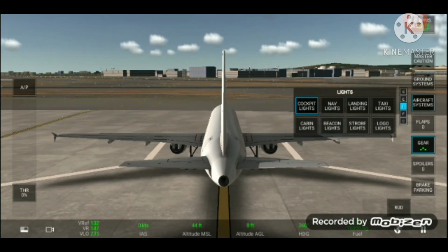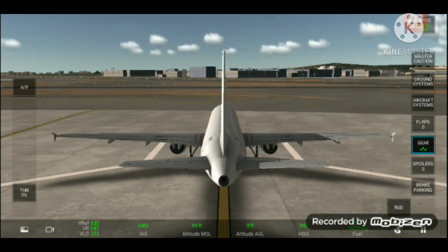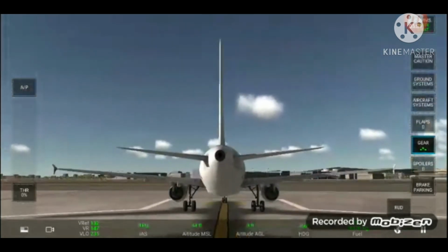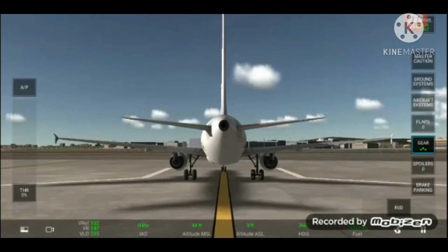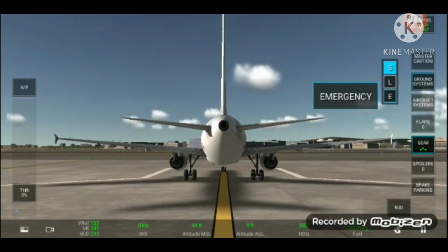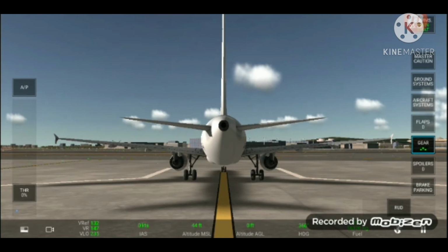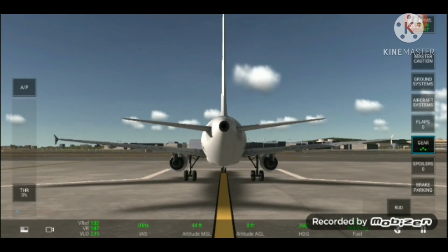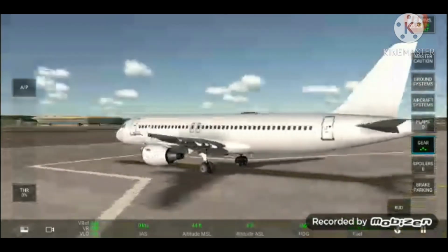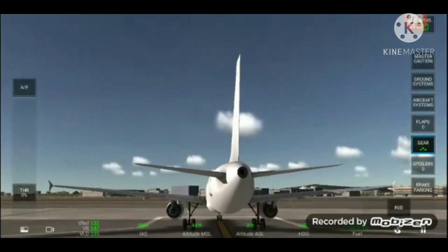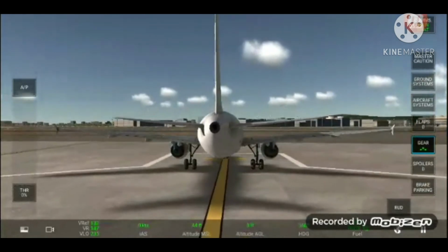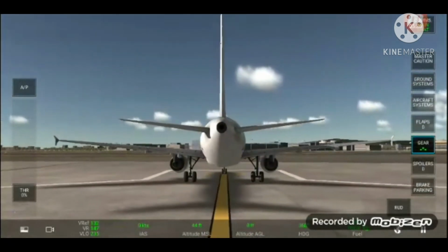Modern planes generally use RATs only in emergency. In case of loss of both primary and auxiliary power sources, the RAT will power vital systems like flight controls linked with hydraulics and also critical in-flight instruments. Some RATs produce only hydraulic power, which is in turn used to drive electric generators. In some early aircraft, even airships, small RATs were permanently mounted and operated a small electrical generator or fuel pump.